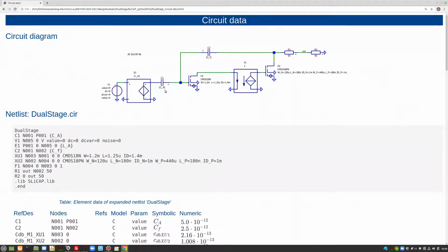So two poles, and you can easily calculate those values and find that the other pole is at about 1 gigahertz. So we have seen the circuit has two dominant poles, and of course a capacitive attenuator at the input in the loop gain. We can select the controlled source F1 as loop gain reference, and then plot all the parameters of all the curves of the loop gain.